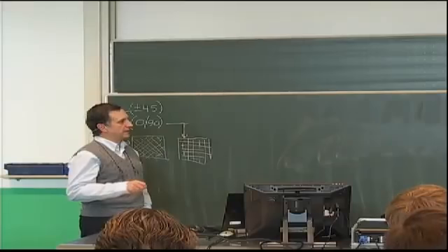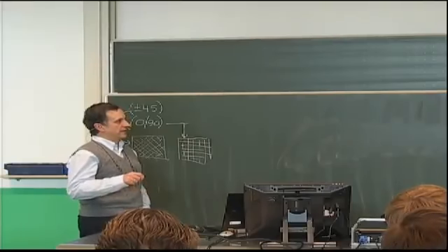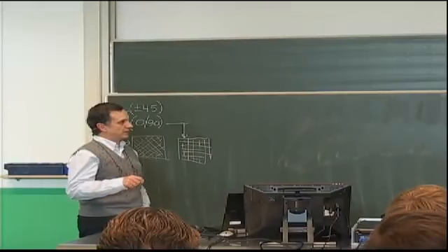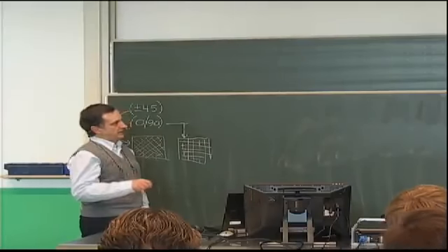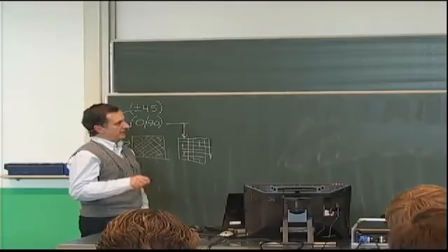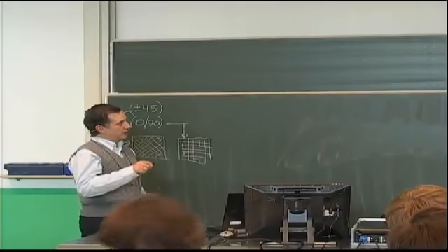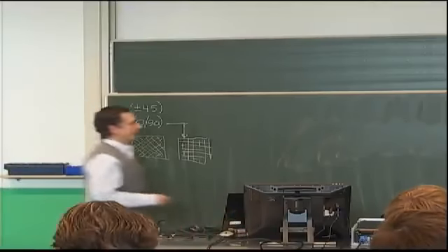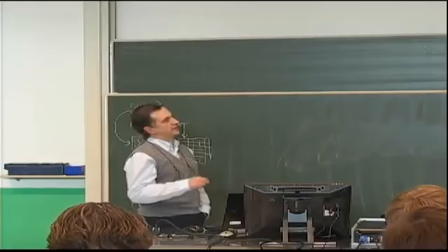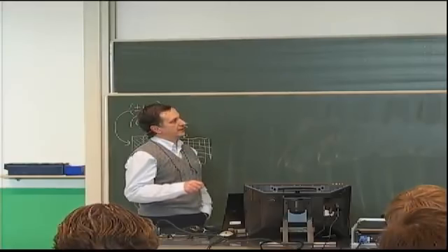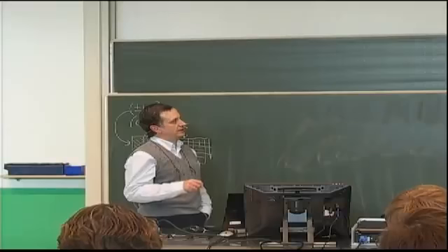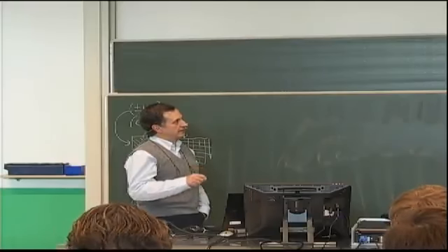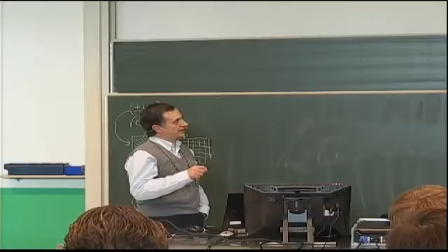And I'm plotting it as a function of distance, x over a. So x over a equals 0 is where the force is acting, and x over a equals 1 would be at the other end of the plate. And it goes to some value, which is the axial stress divided by the far field stress. So basically, the far field stress here is the force divided by the cross-sectional area. And at the end where the force is applied, we get almost 9 times that value.